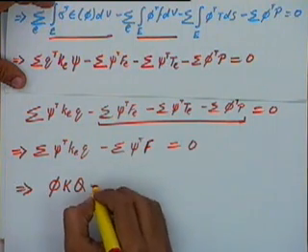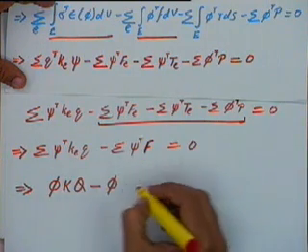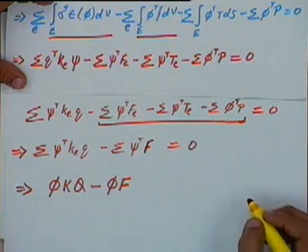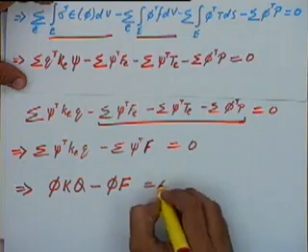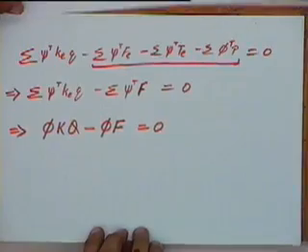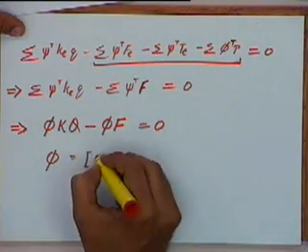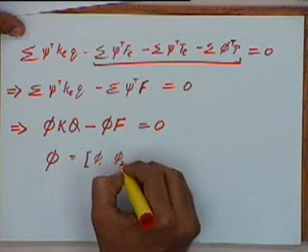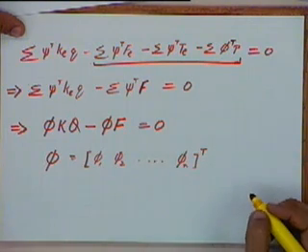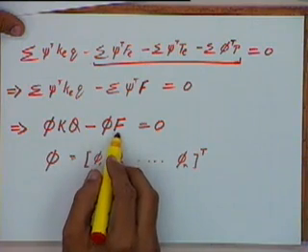This again will be minus this psi, which I am changing to a global matrix phi, and this F I am changing into a global force matrix, and I will say this is equal to 0, where this global matrix phi will be equal to phi 1, phi 2 till phi n if I have n elements. The definition of K, Q and F will be the same as what we had earlier.